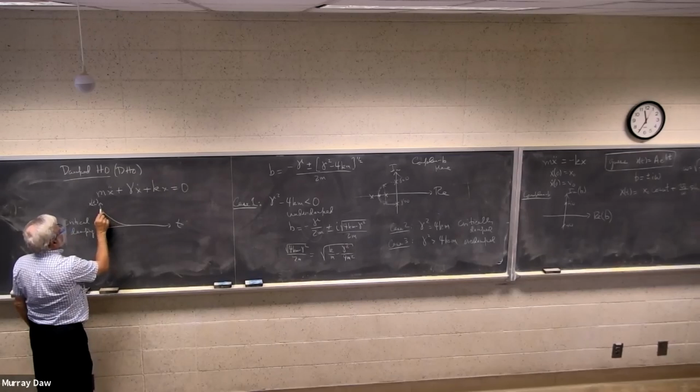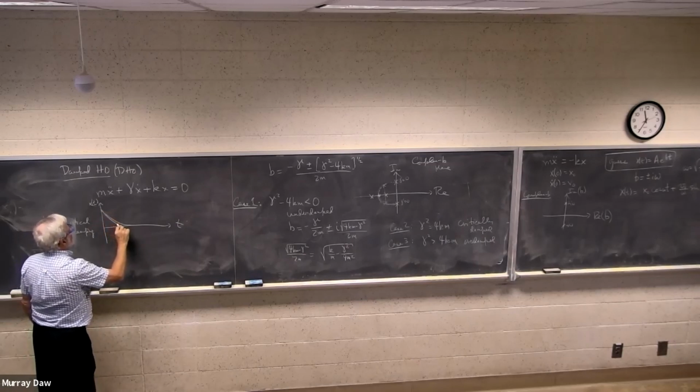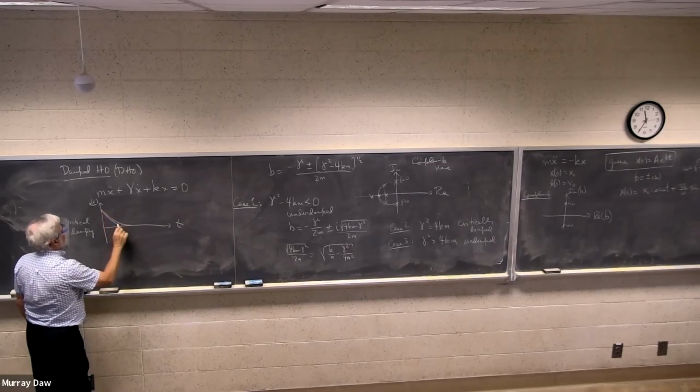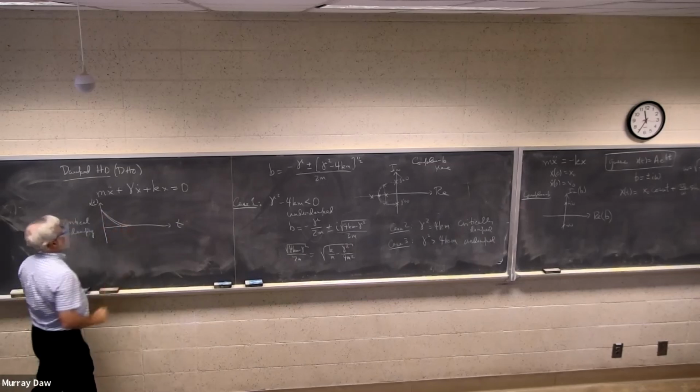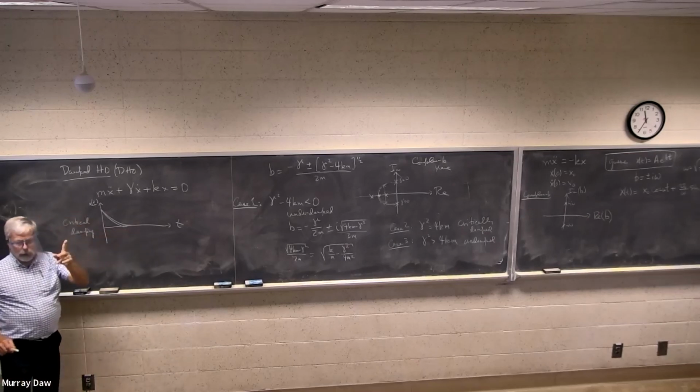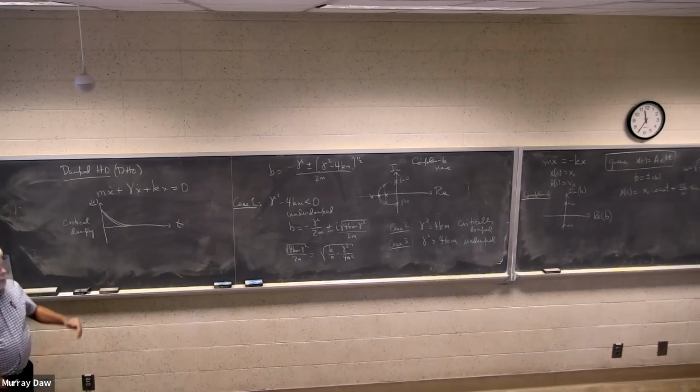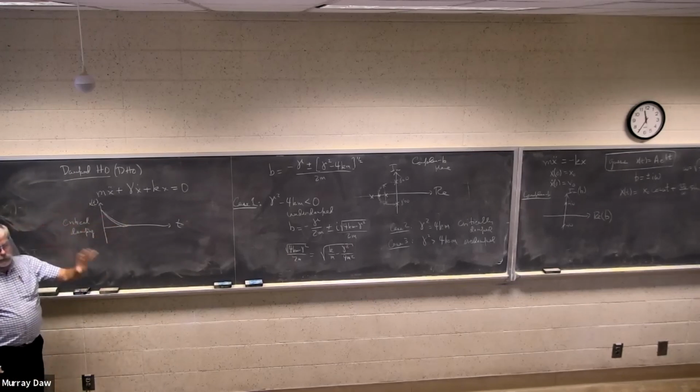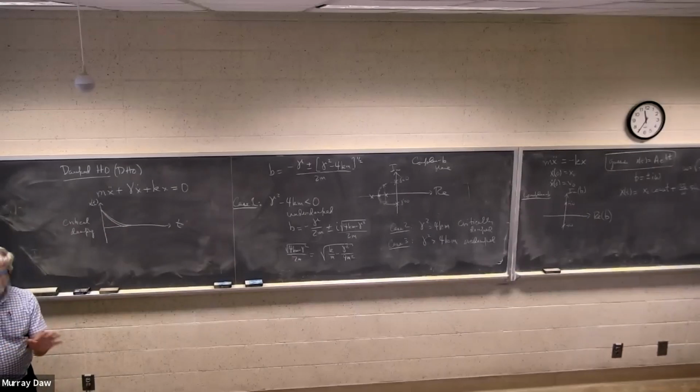If I remember correctly, it may actually shoot over once like that. It's losing energy faster, but it can overshoot, but only once. So critically damped, if you're trying to get rid of the energy without having any oscillation, you want it to be exactly critically damped. The system will just die out without oscillating.